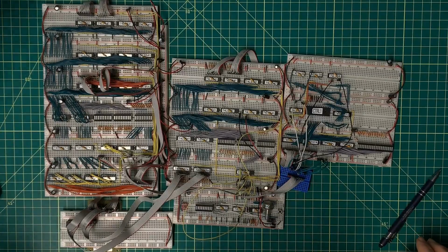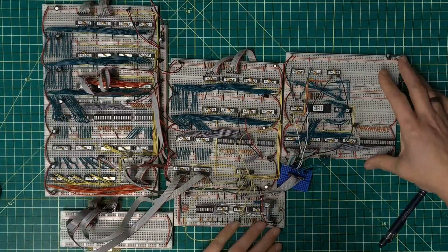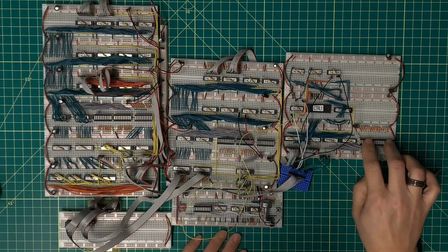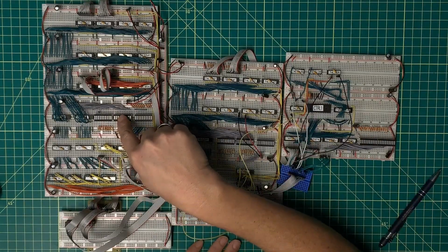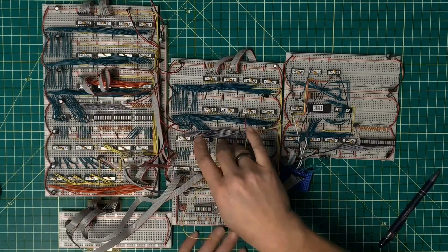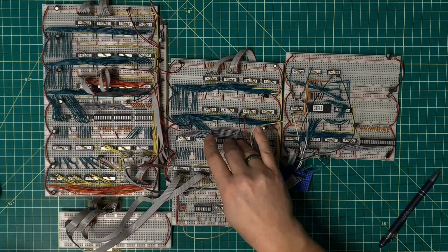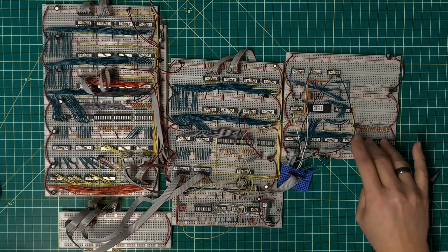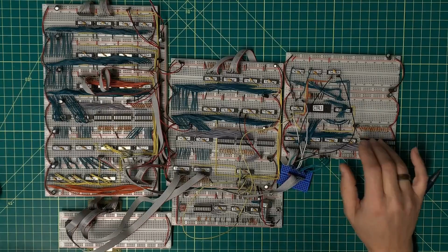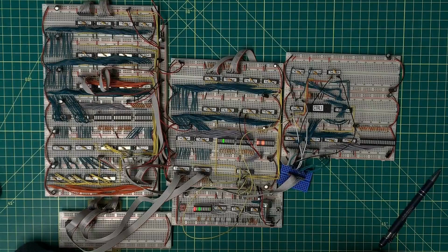So if that is truly set right, then when I apply power, what I should see is the instruction here. I should see the program counter incrementing and latching, and I should see the fetch register showing each address in turn as it increments. The address here will increment, and then the fetch register will increment, and then the instruction register will increment all in succession. And its starting point is not guaranteed to be 0, so we could end up with some crazy starting point, but it should increment from there.